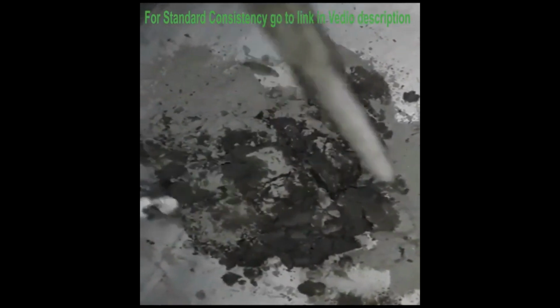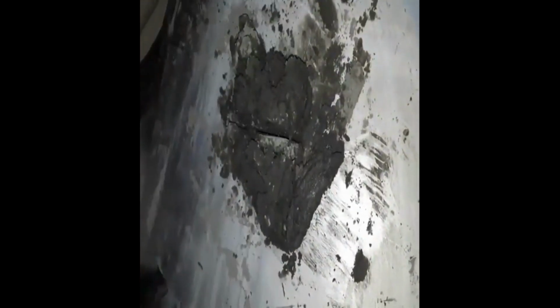Right now we can see the water is getting mixed with the cement and the process of hydration has already begun. All the 4 main compounds, the Bogue compounds, are reacting. The first compound that is reacting is tricalcium aluminate. The second one is tetracalcium aluminoferrite.